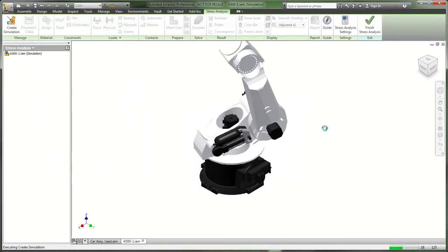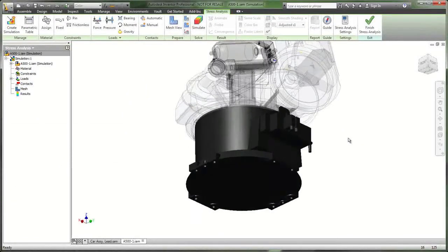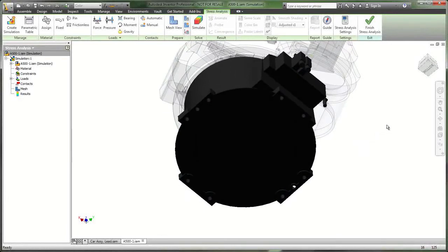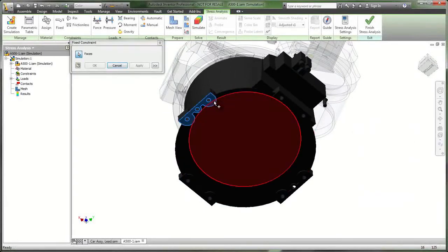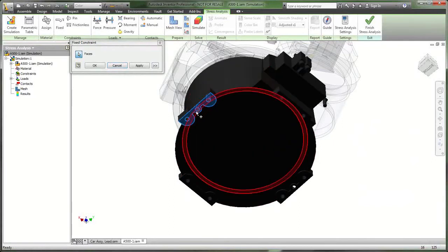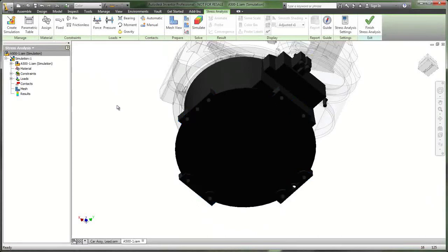At this point, all that is left to do is to set up the static environment for the base of the manipulator. We start by grounding the base to describe how the base itself is mounted to the car of the entire robo-coaster segment. You can select the faces themselves, which are bolted down, as well as the bolt cylinders. These are the cylinders of the holes, which the bolts pass through and therefore represent the portions of this part, which do not move.